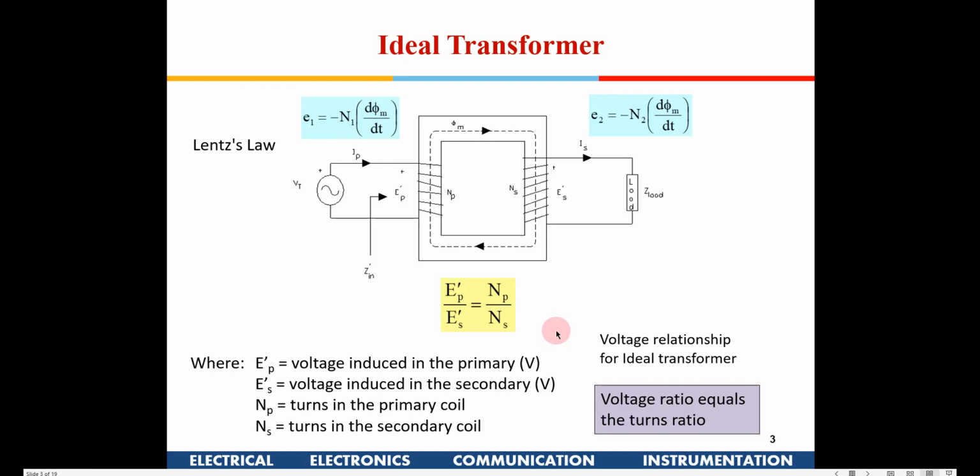Also in the transmission line, we spoke about how when we are transmitting a signal from place A to place B, for a given power, if the voltage is very high, because P is given by VI, then I will be less, so the transmission losses will be lesser. Generally from the source it will be a few kilovolts of supply which will be transmitted from place A to place B, and as you come close to the load, there will be step down transformers at every junction, and by the time it comes to your house, it will be 230 volt.